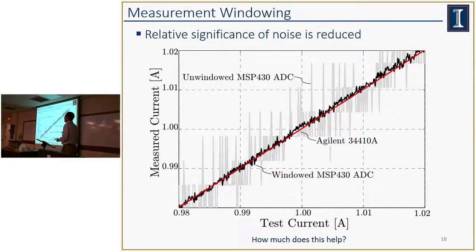We're able to minimize the relative noise that comes into the microcontroller ADC. And then we just append these measurements end to end, and as the current into the converter changes, this gives us some decent resolution over the whole 0 to short circuit current range of the panel.